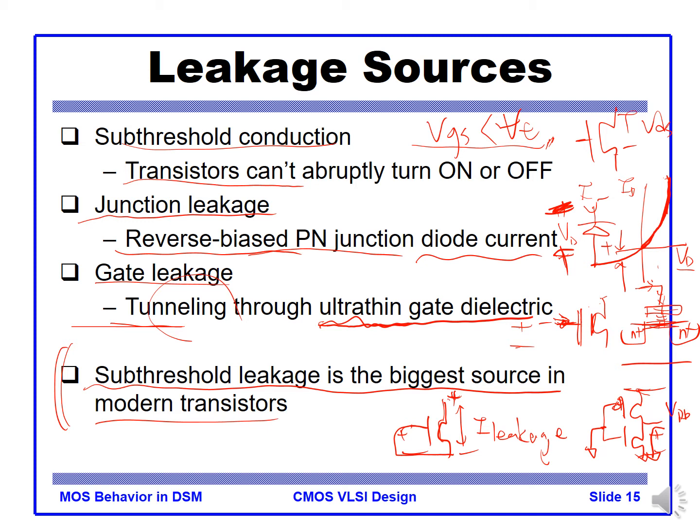So you have to double check and try to minimize the leakage. In modern processes, leakage current is non-negligible. To reduce the leakage current, you have to use a high VT device. If the VTH is larger, we get less leakage current. So if you don't care about speed or performance, you had better use a high VT device to reduce the leakage.